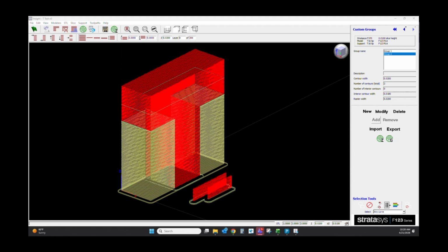And I can't really tell you what Shore value it would provide you by changing that infill. It's kind of a guess and check. But you know, that Shore 92 is pretty rigid. If you try to compress it, it doesn't move much. But if you change that to a 1/4 inch or an 1/8 inch air gap, it does get quite a bit softer.